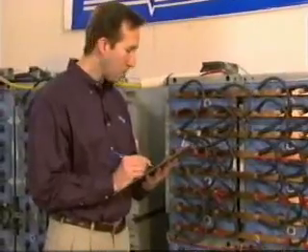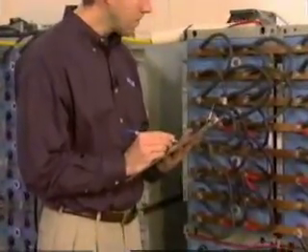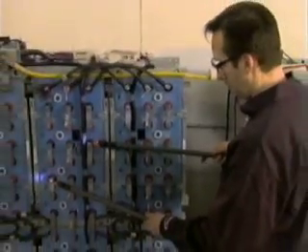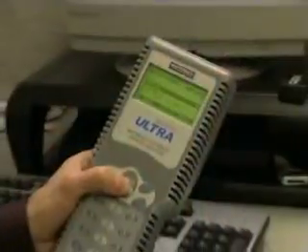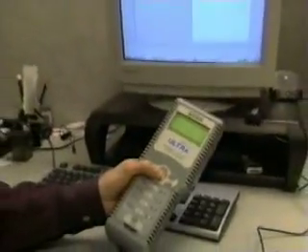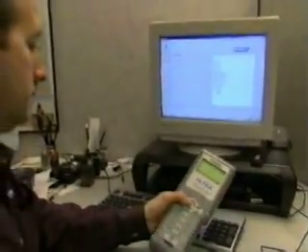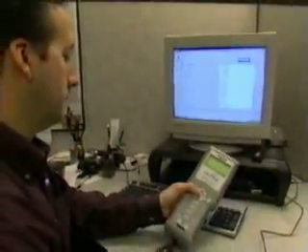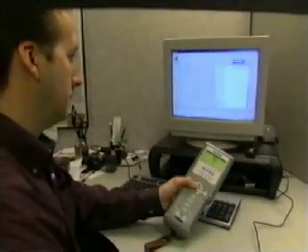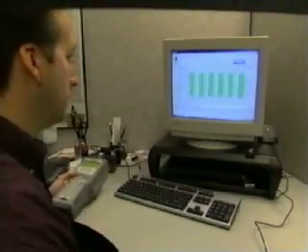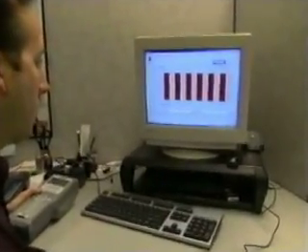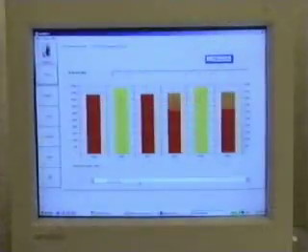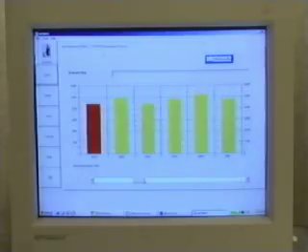It's important to document everything you test and leave a copy of it on site. And be sure to include information on which type of interface you have used, probes or clamps. Another way to archive test results is to utilize a PC for data storage. You can transfer reports, like the string test we conducted earlier, directly to a PC. Using the Inform software included in your kit, you can manage the data and generate reports in formats useful to you and your business.